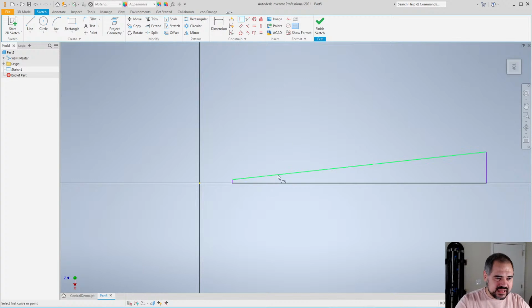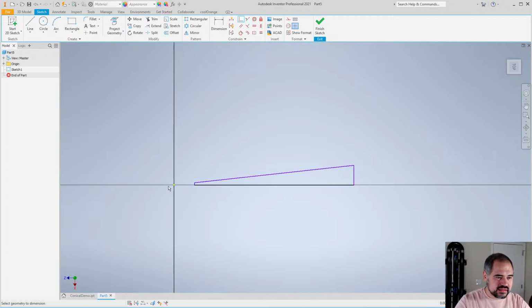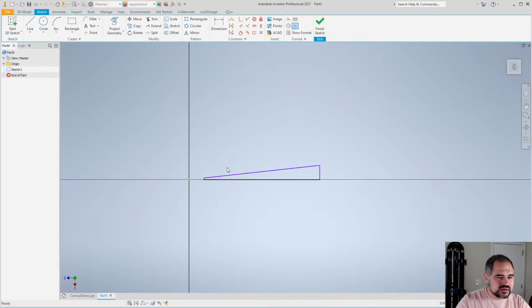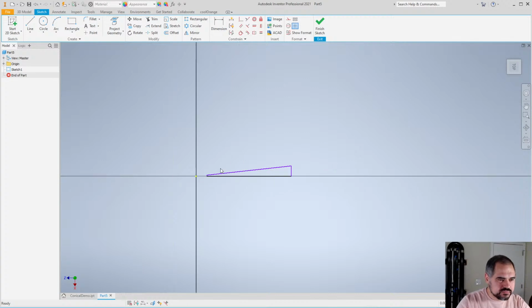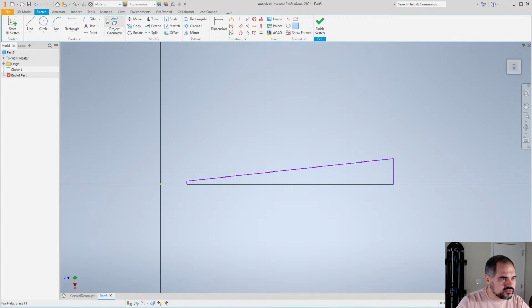I did that by setting a coincident constraint from this hypotenuse to this imaginary point. That way, when you set a length, you're setting the acoustic length of the instrument rather than the physical length of the instrument. That just makes things a little bit simpler overall for me.